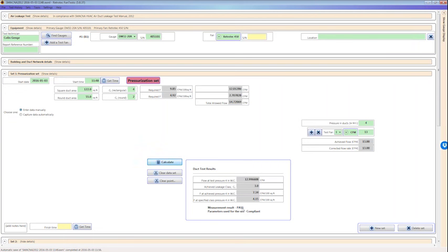You take off this cap, and that will fit directly onto the end of our duct tester, which has a 4-inch collar on it. The 4-inch collar goes onto the Lindab connector with these 2 rubber seals, and you can make your measurements. When you're done, you take it off and put the cap back on. If you ever want to go back and make a measurement again, you can leave that collar on there permanently if you choose to do that. So I thought that was a very interesting way to make that measurement.